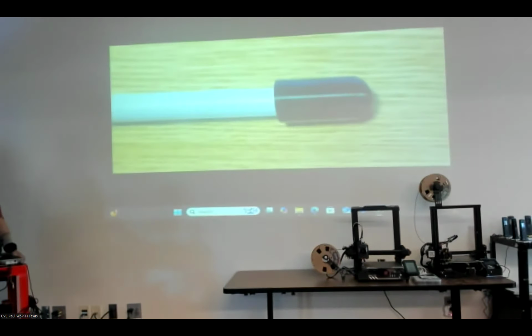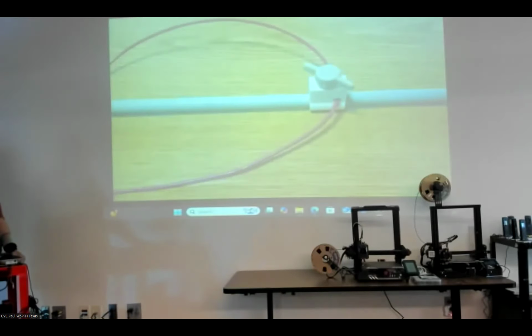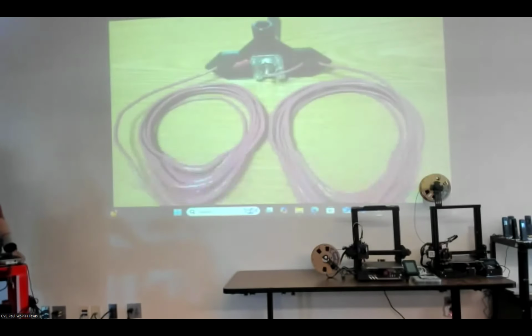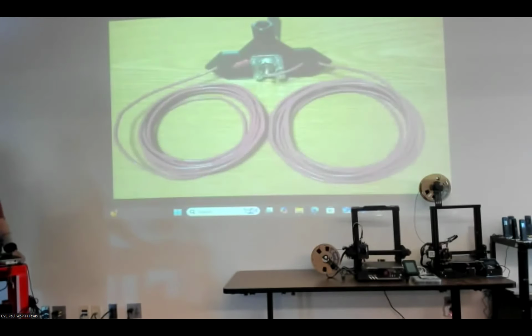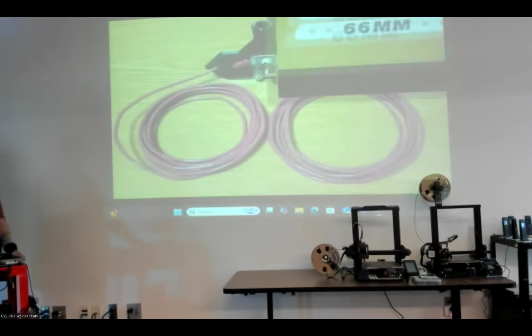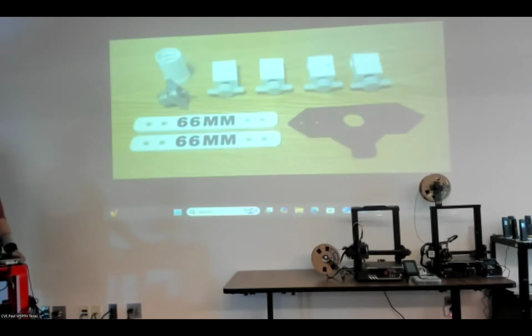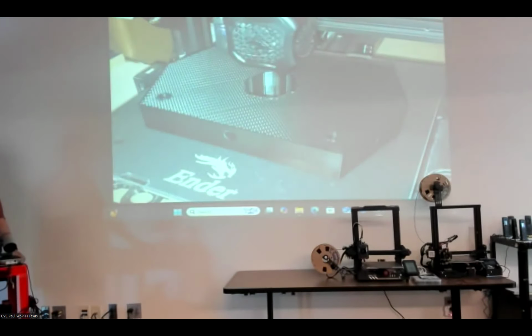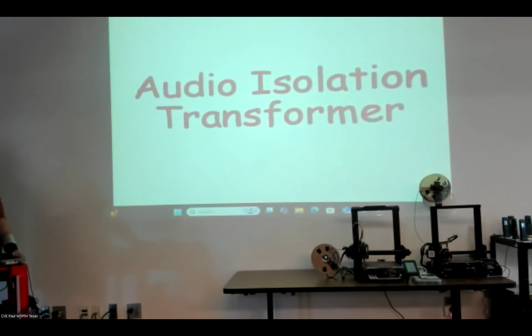The Anycubic Cobra, they claim they can do up to 400. I have a hard time pushing it at best 250 without having any adhesion issues. But they'll both spit out ABS when stock in, no problem. Because ABS is good for an outdoor type of plastic, and out of the ones that he showed there, ABS and PLA is probably the only ones that can be glued successfully.